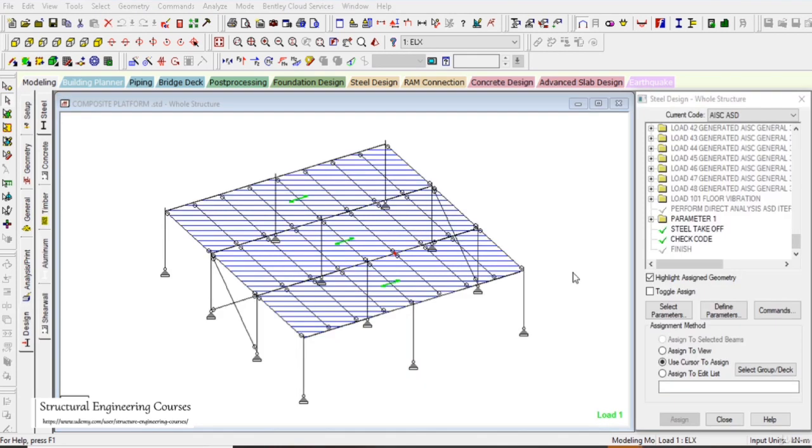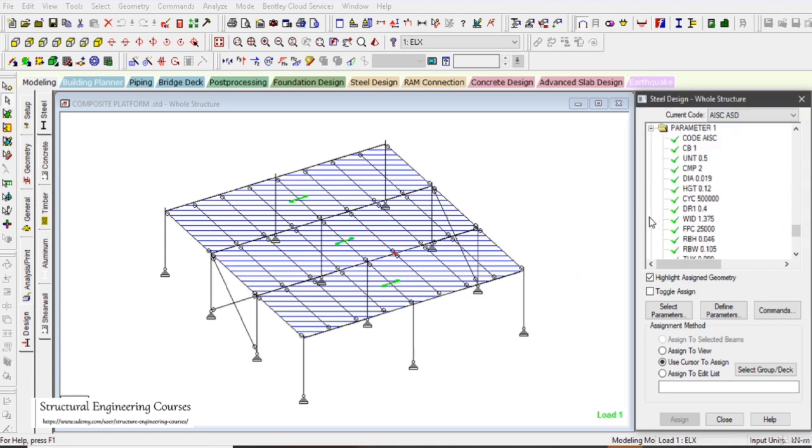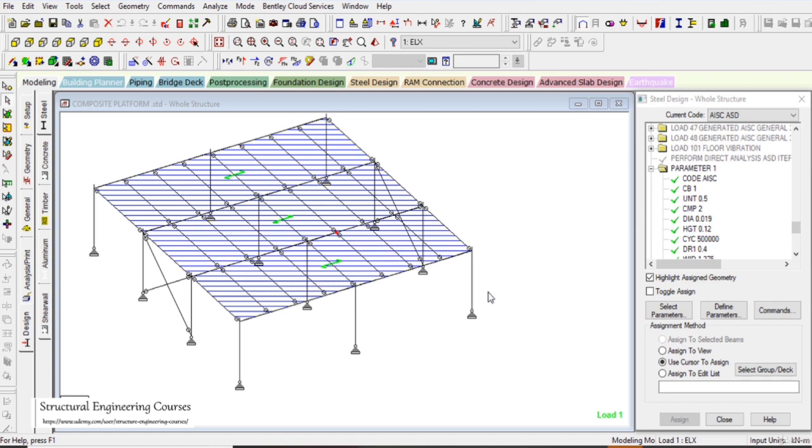Now that we have studied everything about composite steel construction as per the AISC ASD, there is one concept that is still pending, that is how we can check for the deflection as per STAAD. Most people ask me what exactly the DJ1, DJ2 concept and DFF concept is. So I want to explain it in this lecture itself.